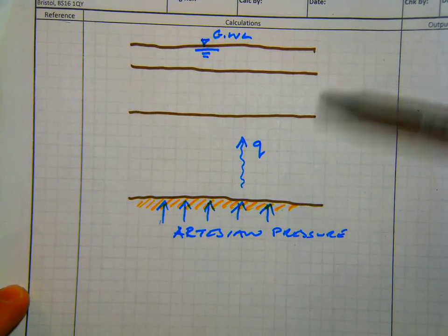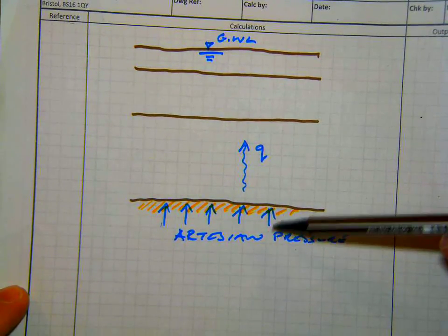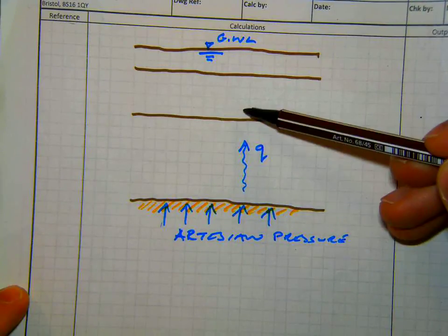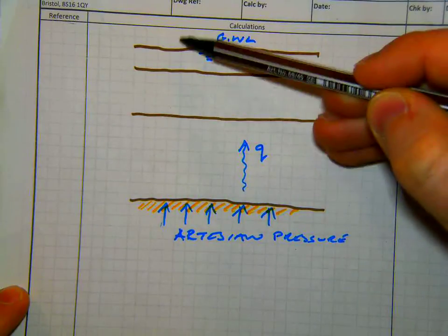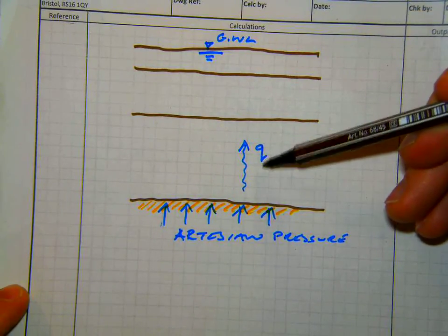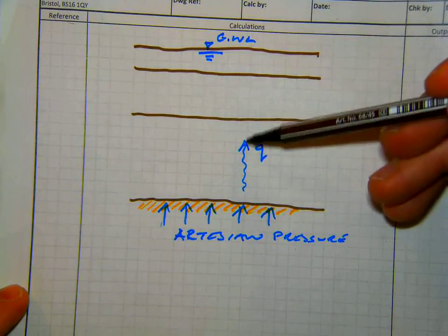There will inevitably be an excess head. The pressure in the water in this gravel bed is such that it causes a flow upwards. If we were to drill a borehole down through the strata, the water would come above the ground surface. So this water flowing upwards has got to combat the downward pressure of the groundwater flow.